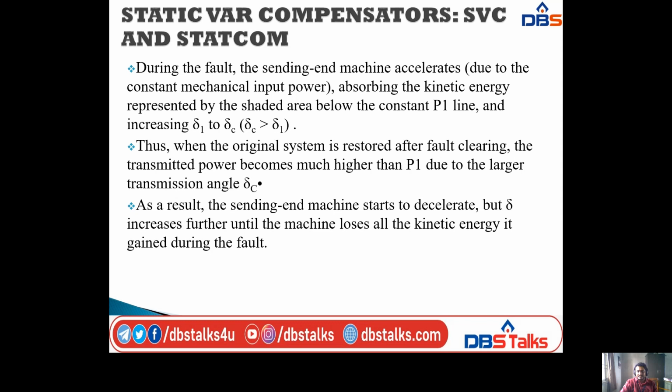As a result, the sending end machine starts to decelerate. During the fault condition the sending end machine accelerates, but after fault clearing the sending end machine starts to decelerate. But delta still increases, as in the previous case also. In this case also, the angle delta increases further until the machine loses all the kinetic energy.